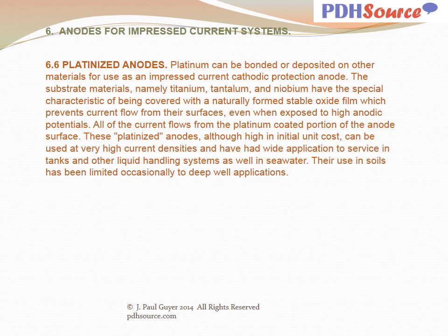The substrate materials, namely titanium, tantalum, and niobium, have the special characteristic of being covered with a naturally formed stable oxide film which prevents current flow from their surfaces, even when exposed to high anodic potentials. All of the current flows from the platinum-coated portion of the anode surface.